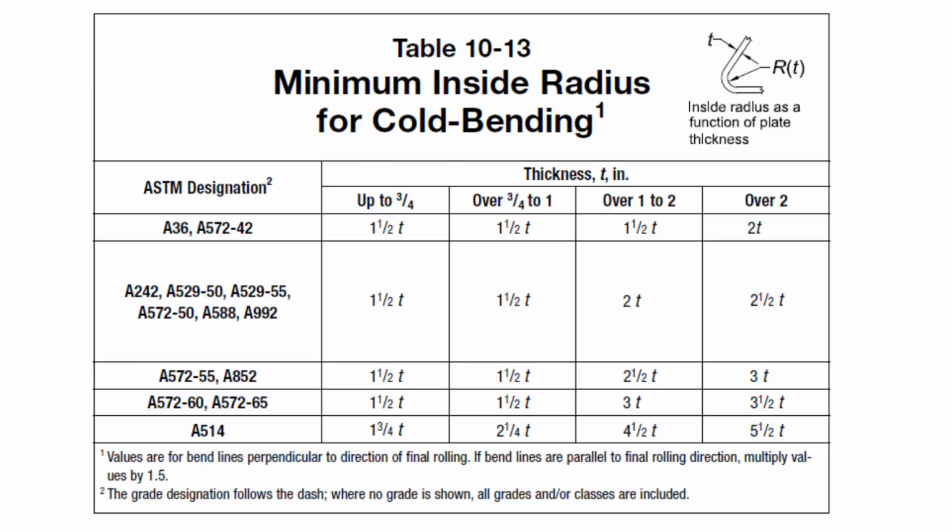So the question becomes, what should be the inside bend radius based upon the thickness and the material of construction? Fortunately, there are several resources available that provide tables showing the relationship between the inside bend radius, the thickness, and the material of construction. Let's have a look at some examples. Here, this table provides the minimum inside bending radius for various thickness and various alloys of steel. The thickness is given along the top of the table, while the various steel alloys are provided in the vertical left column of the table.